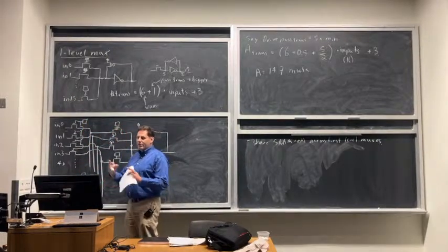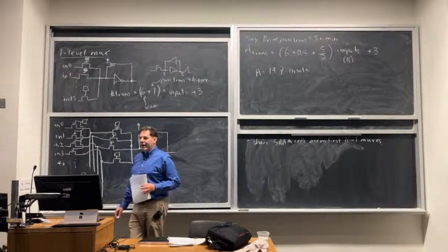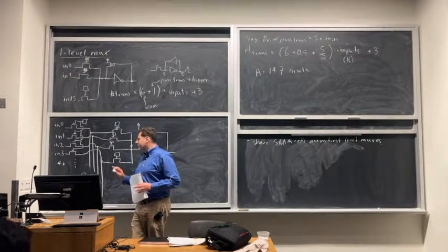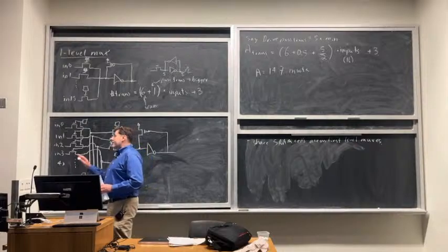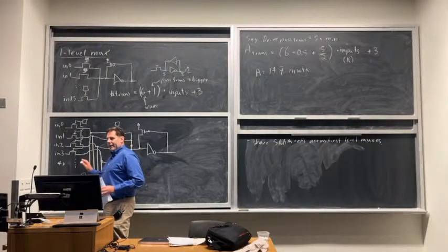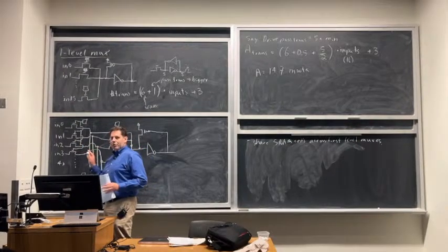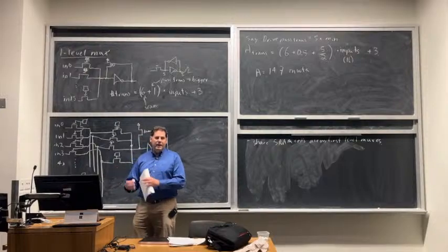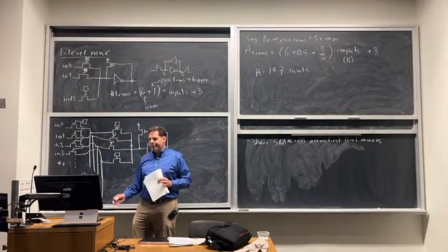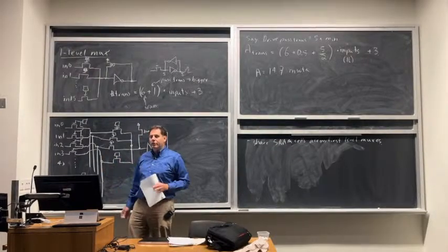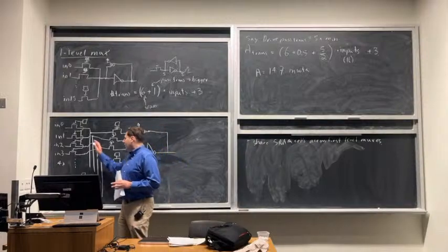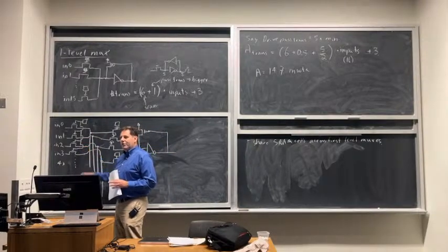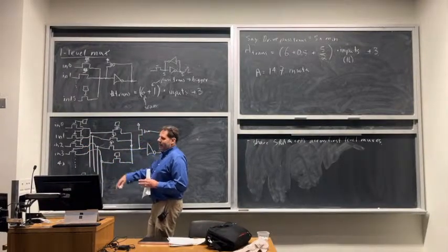But that's the only part of the flow that needs to know how the mux was built. Does that make sense? I guess the other thing that needs to know is the detailed delay models that go into the timing analyzer. How the mux was built has some impact on timing, and that has to be told to that detailed delay extractor. But the optimization algorithms like the router don't actually need to know. This doesn't imply any additional restriction.